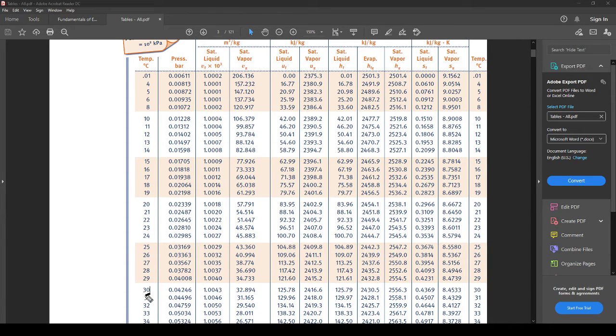You can say, okay, I know it's compressed, but if you keep the temperature the same, these things don't change, not very much. So essentially what they are trying to say is that if you go to the saturated liquid value for specific volume at a fixed temperature, that value that I've circled right here doesn't change very much with pressure.